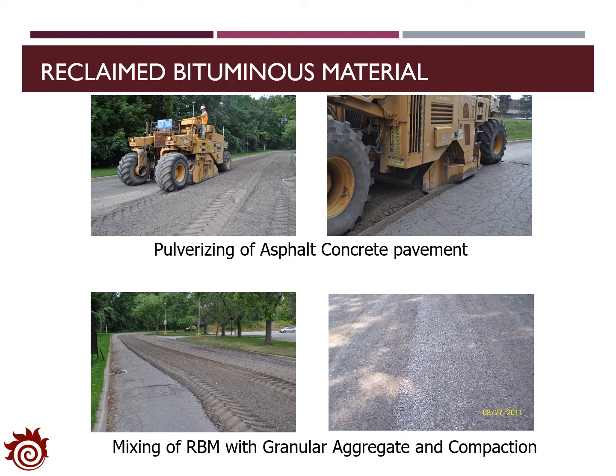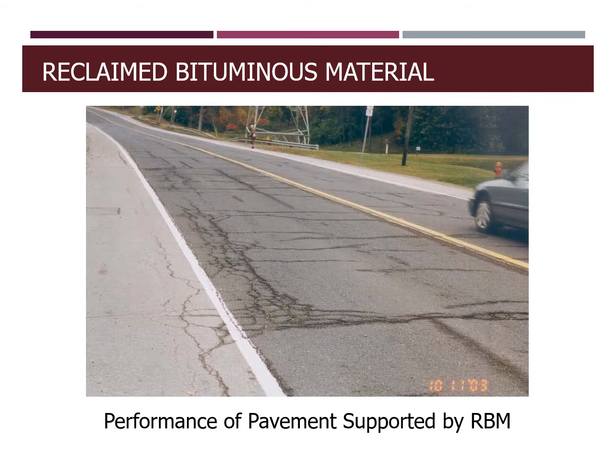There are a lot of advantages of using reclaimed materials in the base course design. The most significant benefit is the low cost of the pavement, especially reductions in materials and labor cost. However, the drawback of these materials is also obvious, as the quality of the reclaimed materials is lower than the original material. It will not be as durable as the original asphalt. In that sense, it will cause more cracks and potholes on the surface.